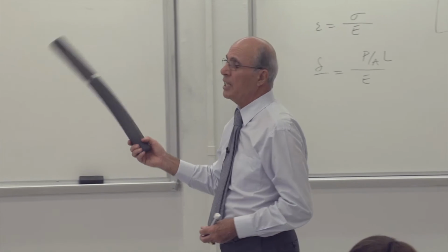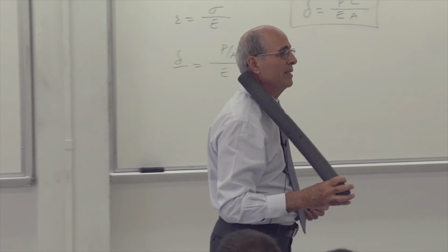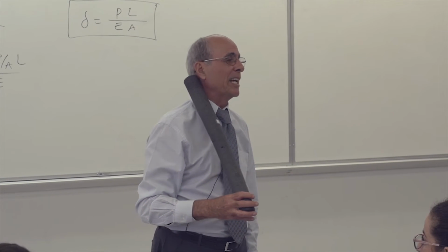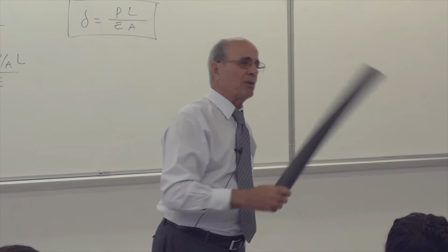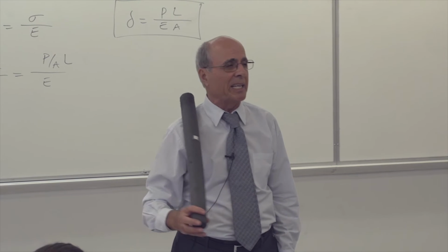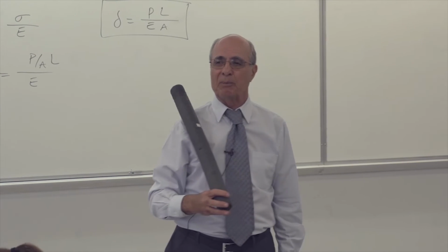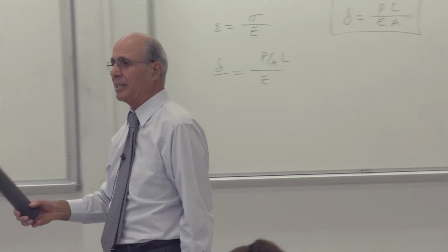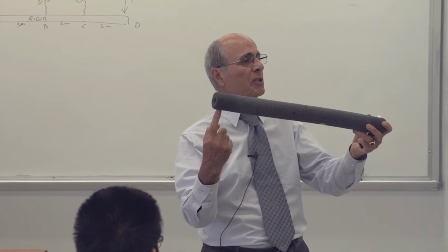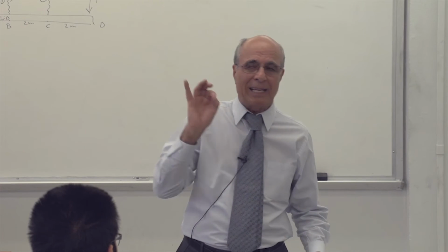Do you know why at A, which is a pin, you put AX and AY? Why do you put AX and AY there? You put AX and AY there because it is resisting against the motion of moving upward and horizontally. Everybody understand that? In statics, I teach statics that way. If this is free to go, it goes. If I put a support here, it's no longer free to move that way. Yes or no? That's exactly the point.